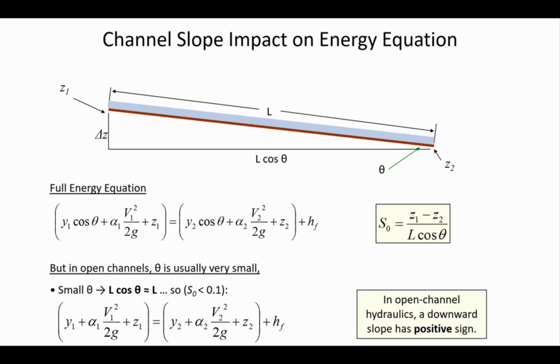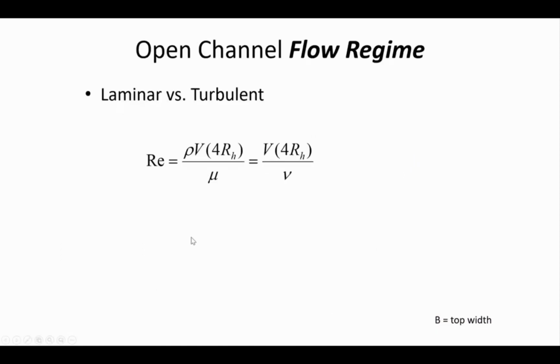We don't say minus 1% or minus 2% for these slopes, because the slope is always downhill. In very, very rare cases you have what's called an adverse slope, where the water is flowing uphill briefly, temporarily, maybe like at a water park, where you have water going uphill just as a novelty for a moment. So by definition, downhill slopes have a positive sign.